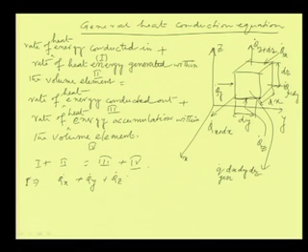All the rates of heat transfer entering into the volume element: q dot x, q dot y and q dot z. Then what is term 2? Term 2 says the rate of heat generated within the volume element. So, we have already written that it is q dot generated into dx, dy, dz. Now, what is term 3?